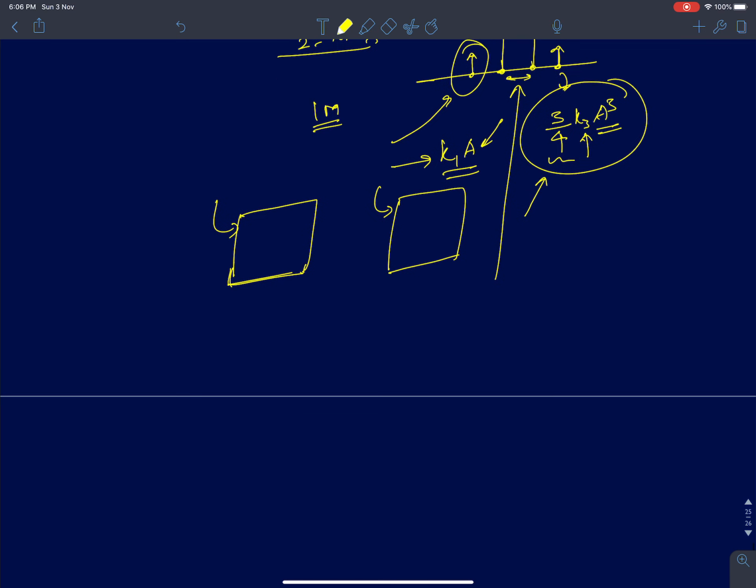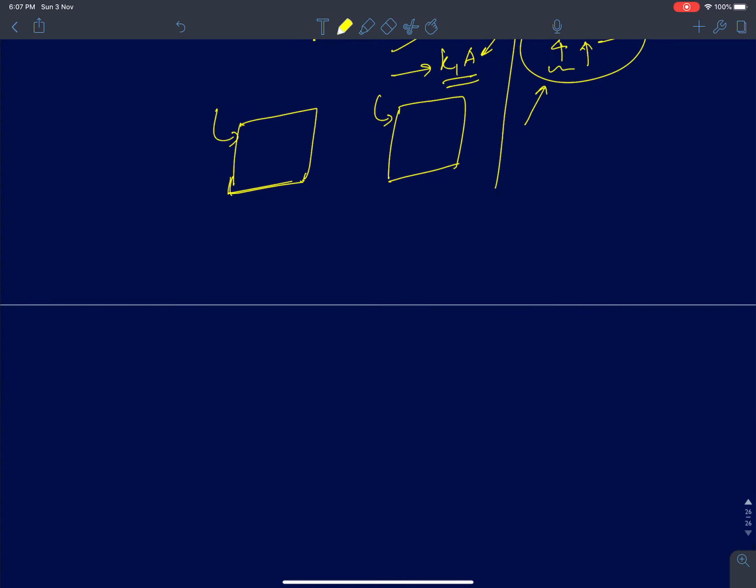Compression point I can even define for low frequency amplifiers, but intermodulation is mainly useful only in RF circuits. Why is that? RF circuits are mostly very narrowband systems.